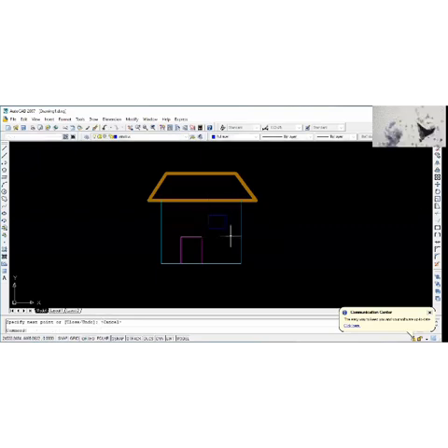So you can see what layers properties toolbar has done. Different colors, it helps to organize drawing. So now let me remove this, trim it. So I just press TR, enter, and then right click. So now let me open the door, the space here. So now this is a small hut that's been designed using the layers properties toolbar.